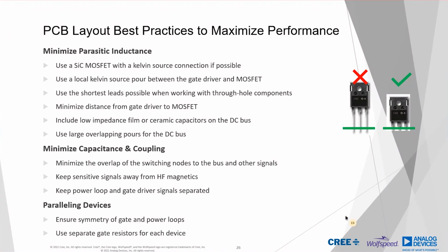So keeping symmetry on the parallel devices is probably the most critical thing there, and using separate gate resistors.